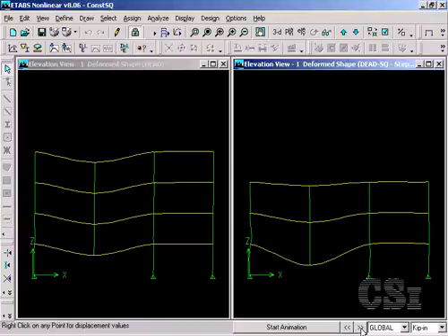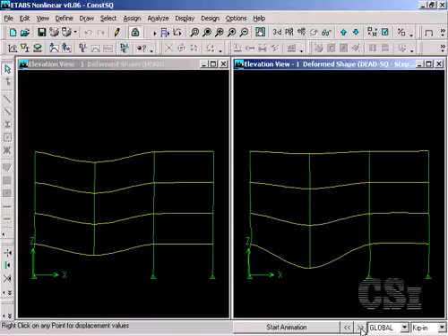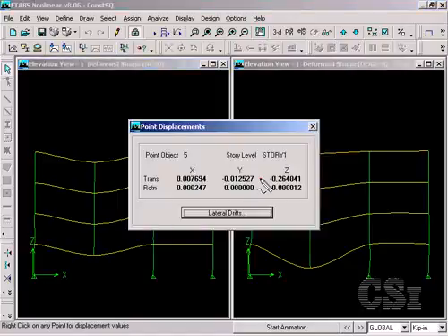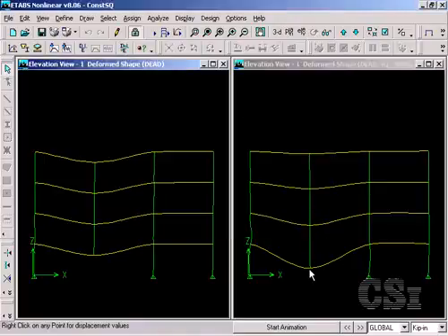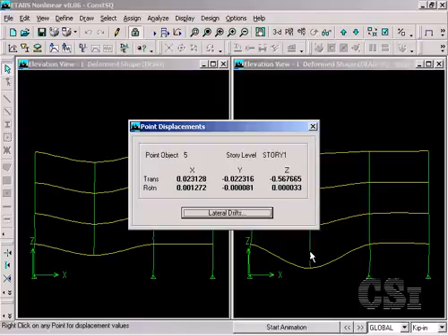Note how the displacement at the transfer girder location grows significantly larger than that of the model where no sequential behavior is accounted for. In fact, a right click on the girder shows the displacement to be approximately 1/4 inch for the non-sequential case, while the displacement is more than double when sequential effects are included.